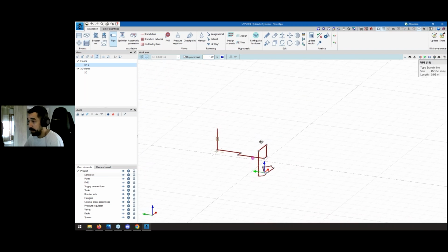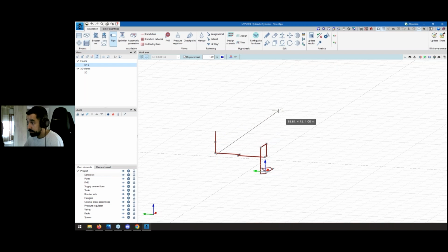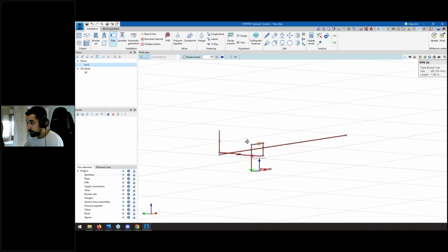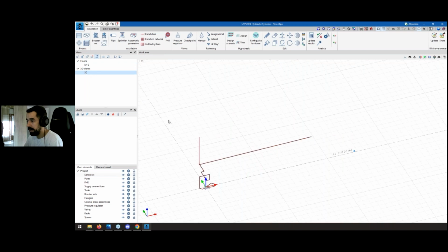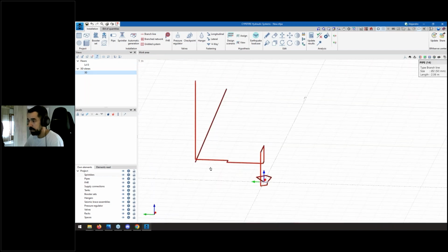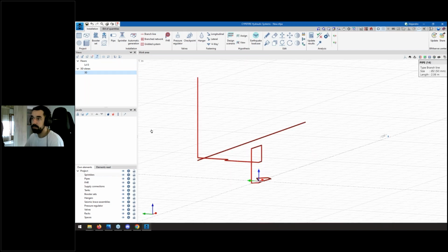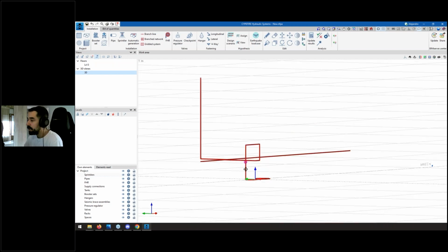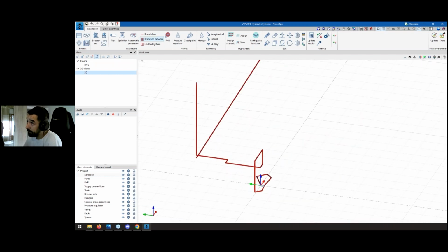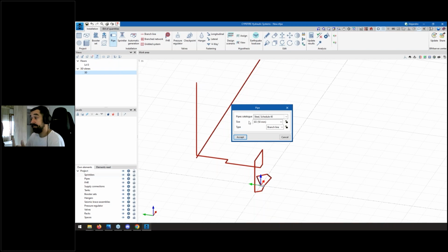So now if I do that, and I go back to 3D, I introduce it on level 0, but with a displacement of 1 meter above this level. Okay, so this is how it works for introducing every element. Not only pipes, also sprinklers, fire hose reel, pressure regulators. Okay, and it's set for later.